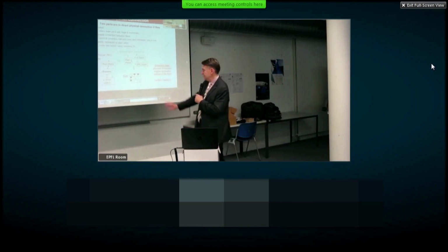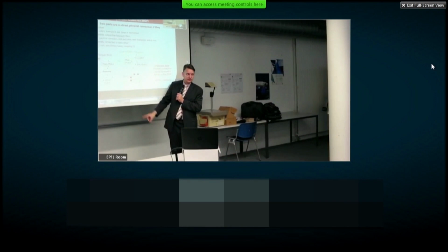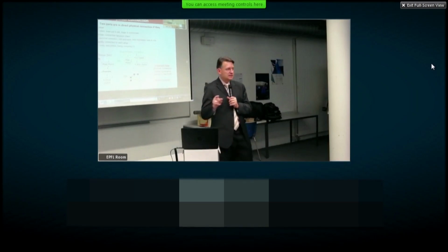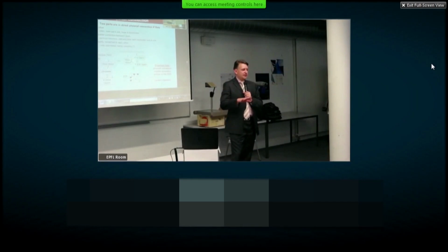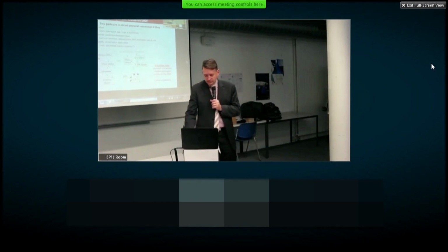And then if we show this as a mini DSM here, 1 connects to 2, 1 connects to 3, but 2 and 3 do not connect directly with each other. They don't have a direct physical interface. And you can see that because those cells are empty. So physical connection implies symmetry in the design structure matrix that we can build up. Yes, Miriam? Oh, DSM. So DSM means design structure matrix, and I will introduce that in a minute. We've briefly mentioned it before in the class, but I'll get into it in some detail.